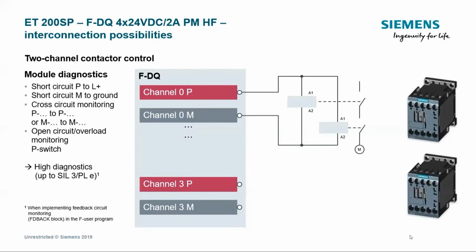For a lower safety level, of course, you need to perform some calculations to see if you can reach that level. So you might be able to use a normal contactor. But if you're not using a standard contactor, for example, if you're using a particular certified or qualified actuator, you don't need to perform any calculation to see if that fits in your application. You know already, because you get the figures in terms of the safety level, or even the probability of failure, directly from the supplier.